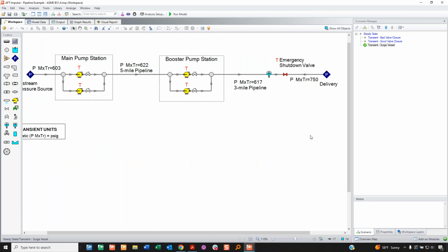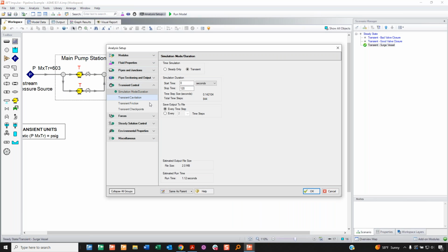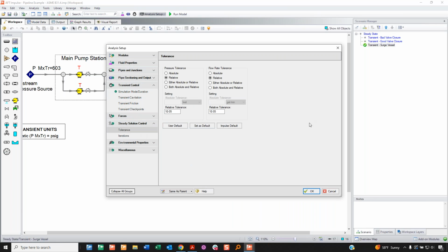I need to go into Impulse, I'm sorry. There we go, that's what I'm trying to do. One reason is that our solution control is a little different in Impulse than it is in Fathom. I hope at least that it's not terribly different, where you draw different conclusions, but we have different settings on the back end where what we consider a converged solution is a little tighter in Impulse at steady state than it is in Fathom.